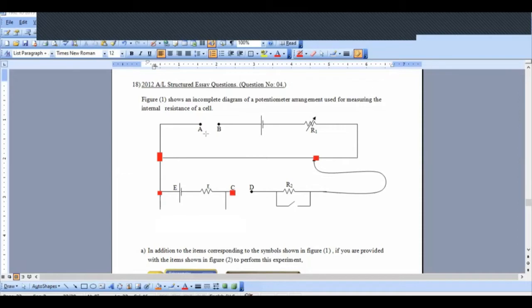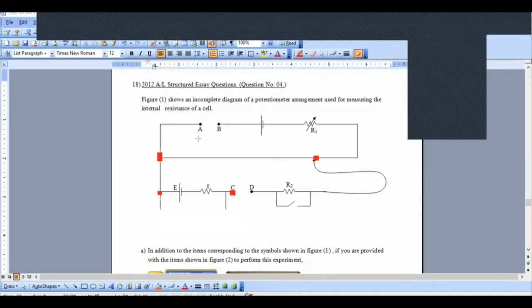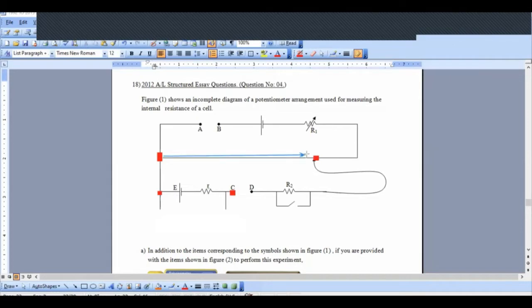So it means if we measure the potential difference across the wire, we should measure this length. We measure this balance length. Balance length L1 is measured, and if this balance length is L, then the potential difference across the wire is KL volt.